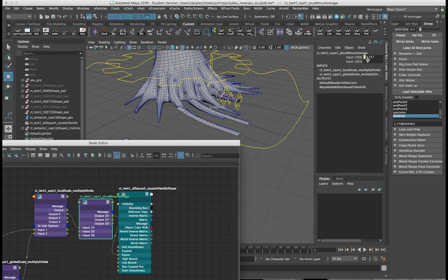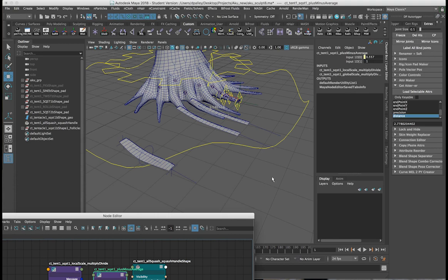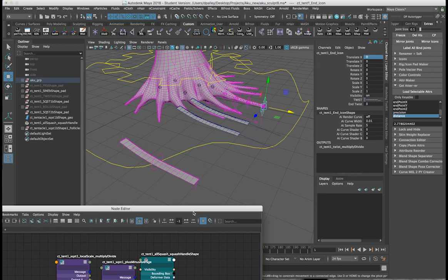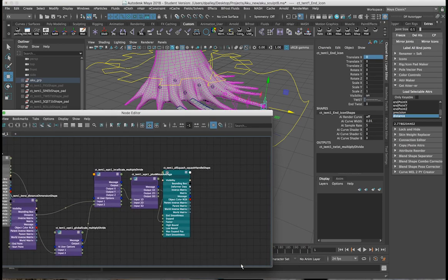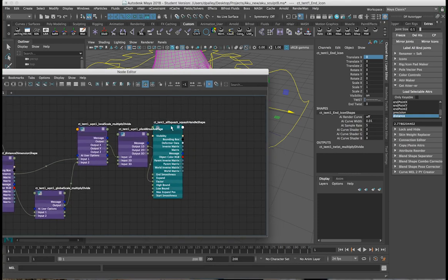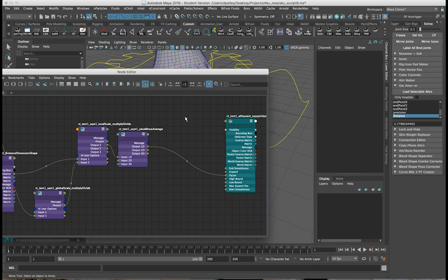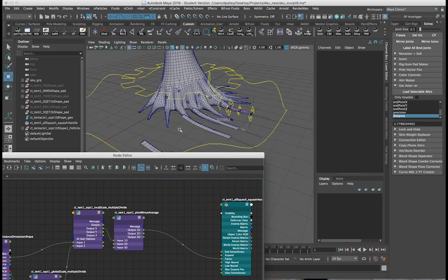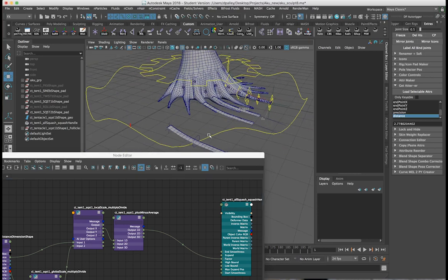Yeah, it's only like 0.5, which isn't really a whole lot of stretch value here. So what I'd like to do is push that just a little bit further if I can. The way we're going to do that is we're going to add a couple of nodes here, and more importantly, one of them is a condition node, so that when it stretches, we're getting the normal stretching that we've already achieved here. But if it's squashing, push it a little bit further.